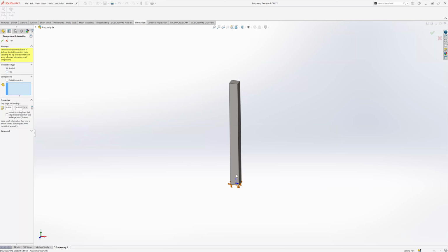A lot of stuff we're going to be doing later, and I'll maybe try to get into this next week, is getting into more dynamic analysis. Obviously, most of the dynamic analysis we're going to be doing is what's called a linear dynamic analysis. I think I talked about linear a while ago, where you have linear materials, stuff like that. So for a linear dynamic analysis, you're not going to have a contact condition either. If you want to calculate a contact condition, you're going to have to do a nonlinear dynamic analysis, which just adds an extra level of complexity to your analyses.